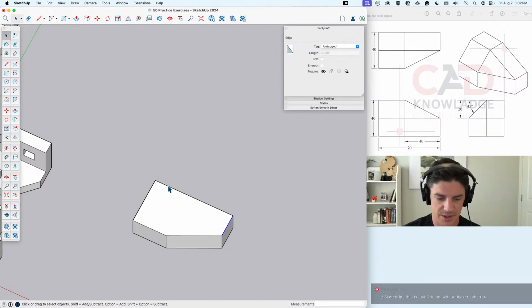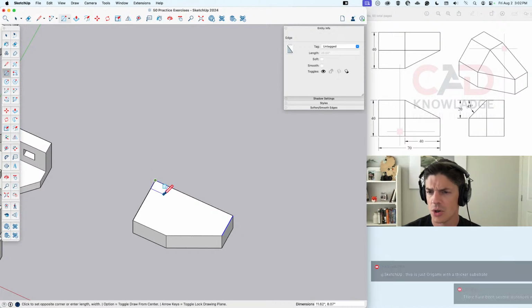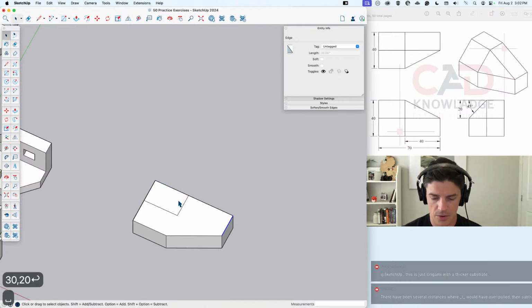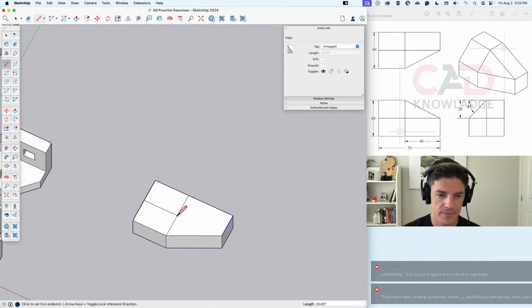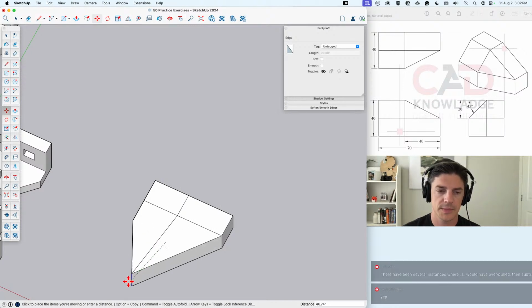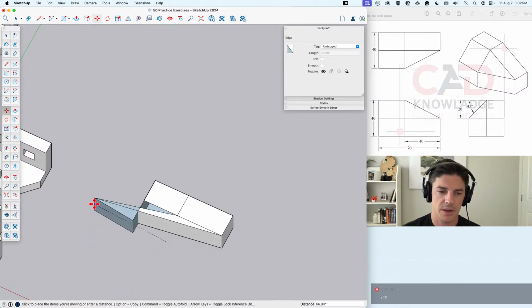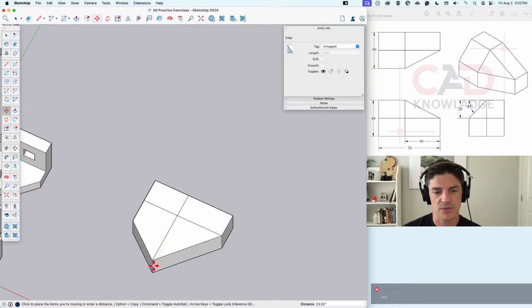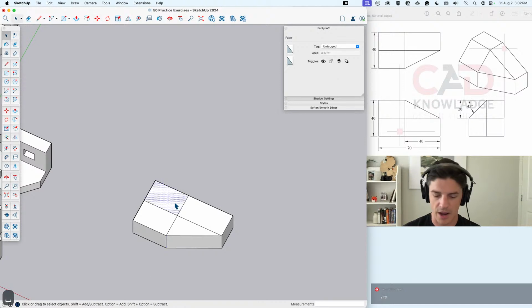Somebody asked what is autofold, and we're going to see it here. It's basically when you move a face instead of using push pull, it's connected. If it's not grouped separately, it's connected to other edges and faces, so you can use that to almost distort the geometry. It's almost like folding origami, and that's why we call it autofold, because it just happens. Some people start using SketchUp and they're like, why is everything sticking together? But I think it's really helpful. Let's try it out in this.